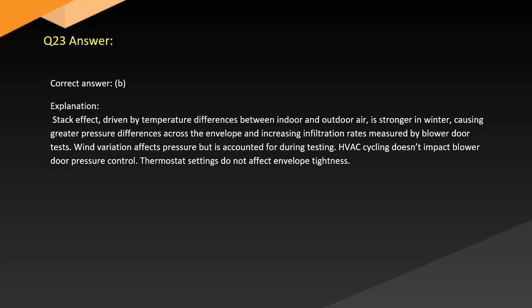Answer. Correct answer: B. Explanation. Stack effect, driven by temperature differences between indoor and outdoor air, is stronger in winter, causing greater pressure differences across the envelope and increasing infiltration rates measured by blower door tests. Wind variation affects pressure but is accounted for during testing. HVAC cycling doesn't impact blower door pressure control. Thermostat settings do not affect envelope tightness.